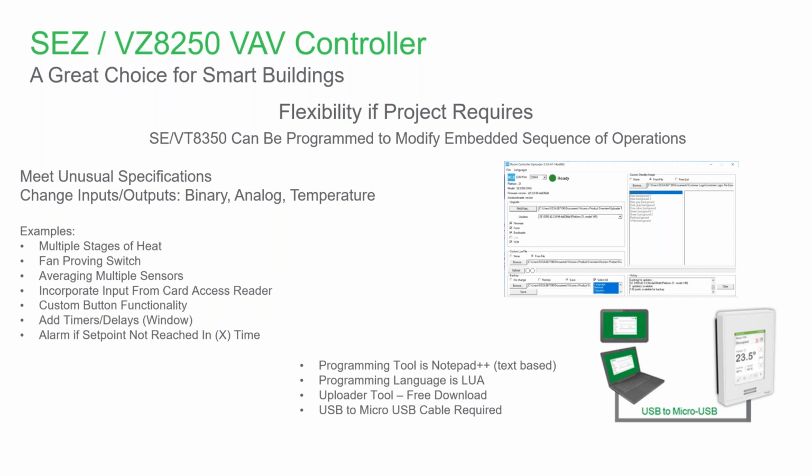And they have Lua in the room controller, and every 24 hours, Lua will go back and reconfigure the set points, realign them. So how many of you out there constantly have, well, you know you want to have set points specifically to what I call a prescribed set point in a building, that they're all over the place on a daily basis. Lua allows you, in a standalone world, to have that room controller sit on the wall and just automatically reconfigure all of that for you all day long.